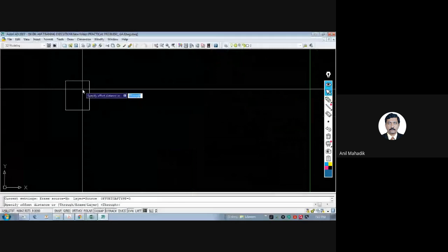And then take the center of the footing here like this. So let me assume the center. I'm just drawing this diagonal for the center, and then move whatever you have drawn. Now this, my first column footing size, is this. So let's paste this on this column layout. And then remove this diagonal. It was only for reference. And then you can give the dimension to this like this. In a similar fashion, you can put all the footing sizes on this as per the design.